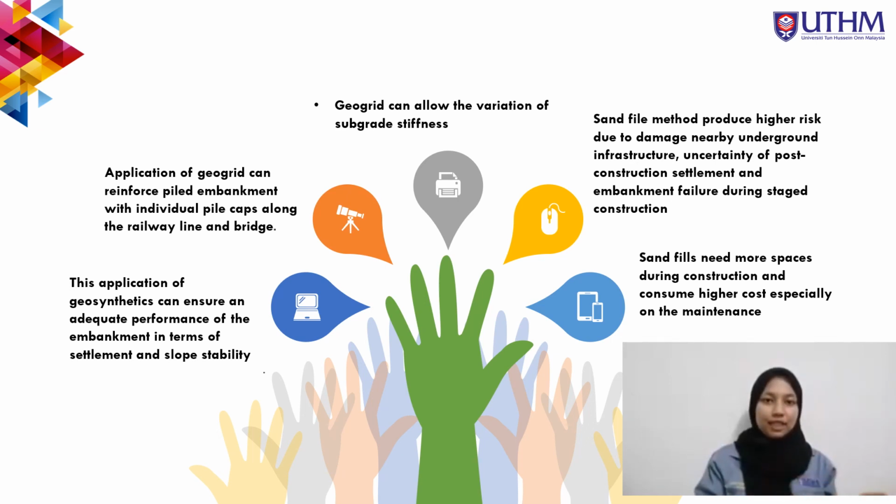This application of geosynthetic can be compared with the conventional method, which is sandfill, and the sandfill method will produce a higher risk due to damage to nearby underground infrastructure, uncertainty of post-construction settlement, and also embankment failure during staged construction. Besides that, sandfill also needs more space during construction that could damage the transport routes and also compromise safety. In terms of cost, sandfill actually consumes higher cost, especially on maintenance, compared to the pile embankment.